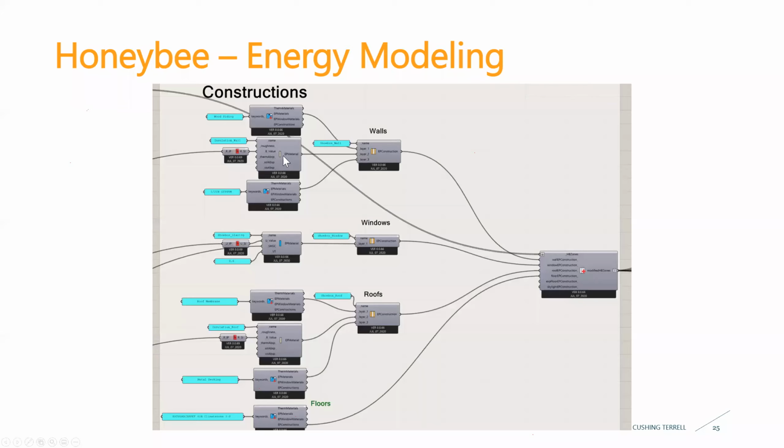And then for insulation, I just pulled in kind of a default opaque material, and you can assign all the material properties. Then I added that as layer 2, and then I added some gypsum, just searched through the EnergyPlus material library, pulled out the gypsum, put that in, made the wall. And so I did that for all of them. The insulation R values and the window U value are parameters that I'm changing for the iterative energy modeling. You can't see exactly what they are on this, but you can convert from English to SI units again, to make sure I keep everything metric when it's actually going through the simulation.